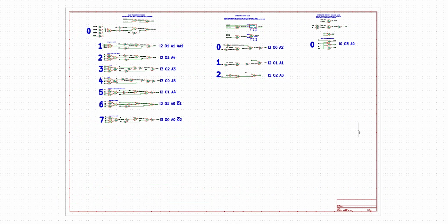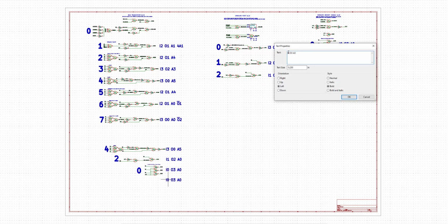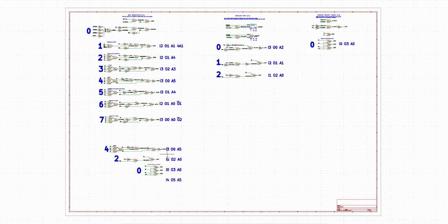Now what I do is I look over these options, and we need to package these into the devices that we can get, the 7400 devices that we can get. So I need to go through and pick one from each column that tend to complement each other. For example, if I take option 4 from this first column, make a copy of that, and option 2 from the second column, and then my option 0, my only option that I have so far in the third column, if I create the total, I need to have 4 inverters, 5 OR gates, and 5 AND gates. So obviously, that's not a good choice because that's only using a quarter of each an OR and an AND.